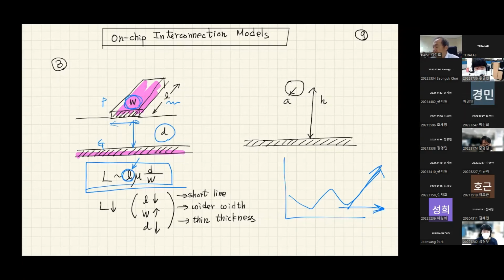That's why I keep saying that at higher and higher frequency, we have to reduce the length of interconnection between decoupling capacitors and I/O switching devices. Also, decoupling size should be very small because the decoupling capacitor itself has self-inductance that will contribute to this inductance as well.